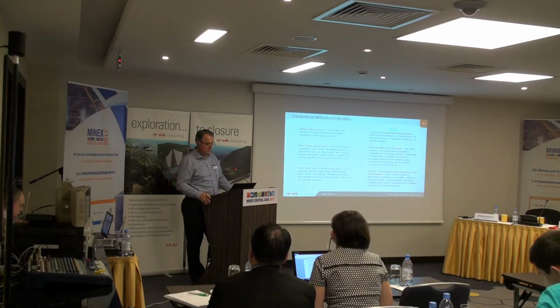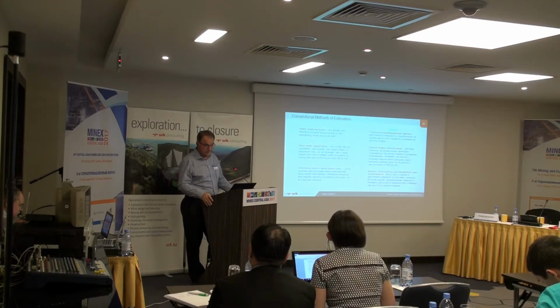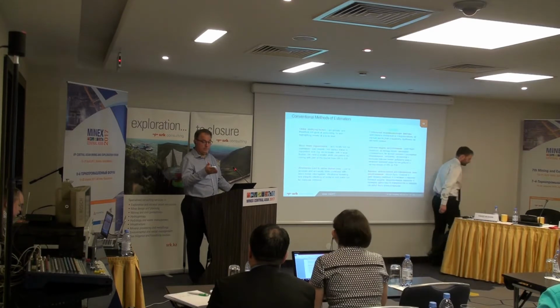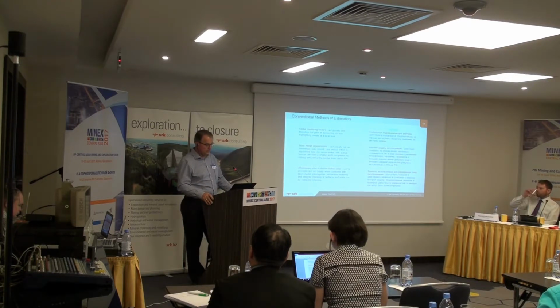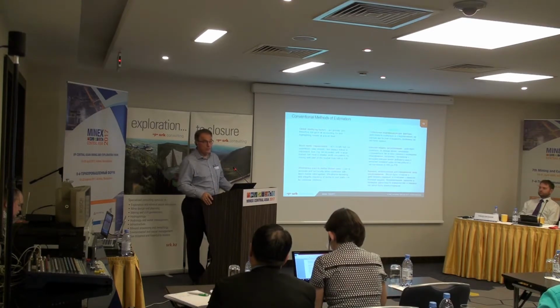One of the aspects of block model regularisation is the relationship with the size of the equipment and the bench height. And there is a relationship, but it also is a function of the type of mining method. Most mining in an open pit with a steeply or moderately dipping ore body should be mined from the hanging wall to the footwall. And exposing an ore body in this fashion often means that you can use a much larger bucket to mine a narrower ore body. It's just the technique applied to mining it.